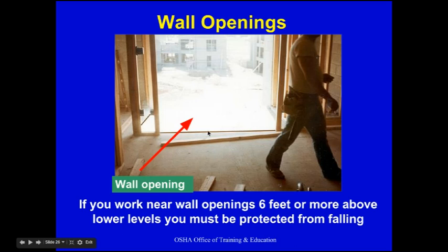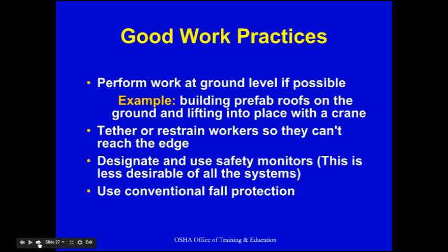And you wouldn't think it's possible, but you're so busy on a construction site doing things that you might actually fall out that side there if you're not paying attention. So throw up 3 2x4s, probably cost you less than $5, and you're keeping your worker safe.